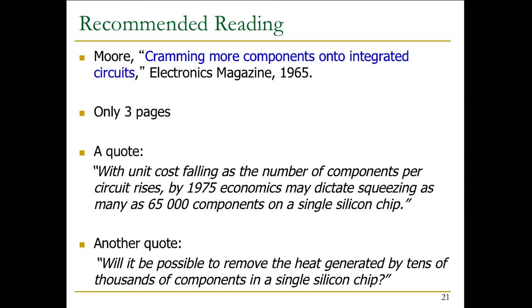Modern chips are not limited by the number of transistors that you place, but by the number of transistors you can keep active at the same time, the number of transistors you can switch. Because every switch leads to energy consumption. If you're switching too much, then you may actually be causing a lot of heat and leading to thermal degradation, right? That's why we can actually put more transistors than we can switch on the chips today.